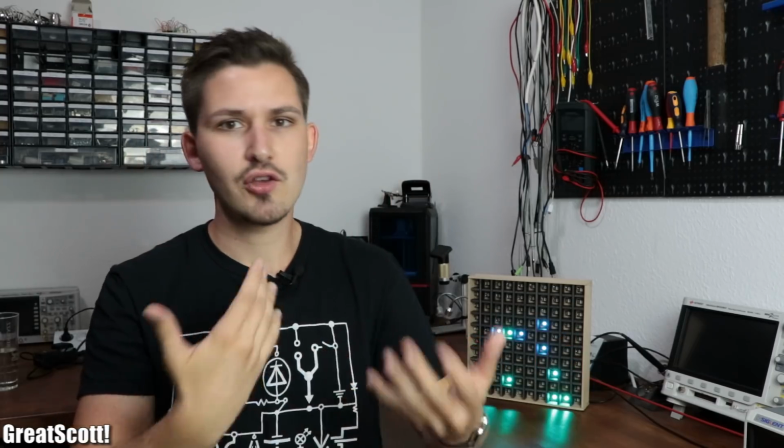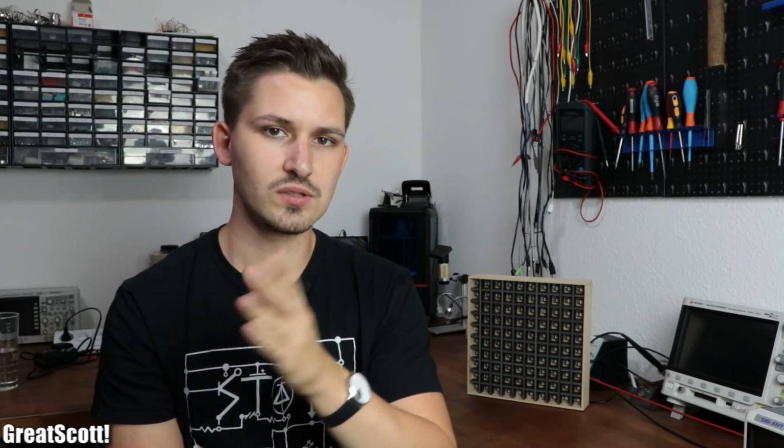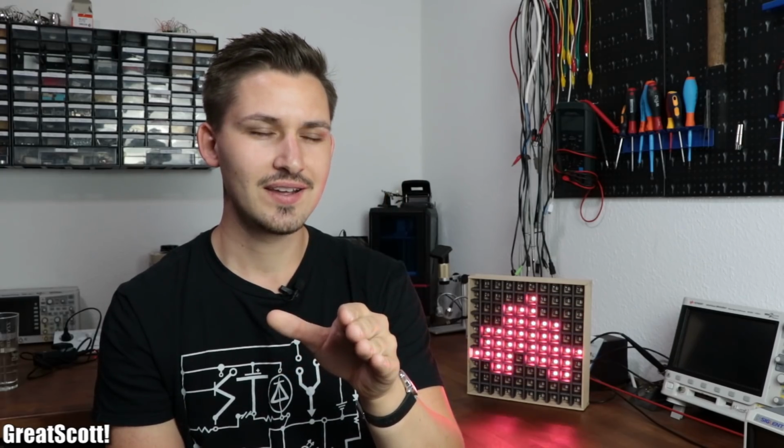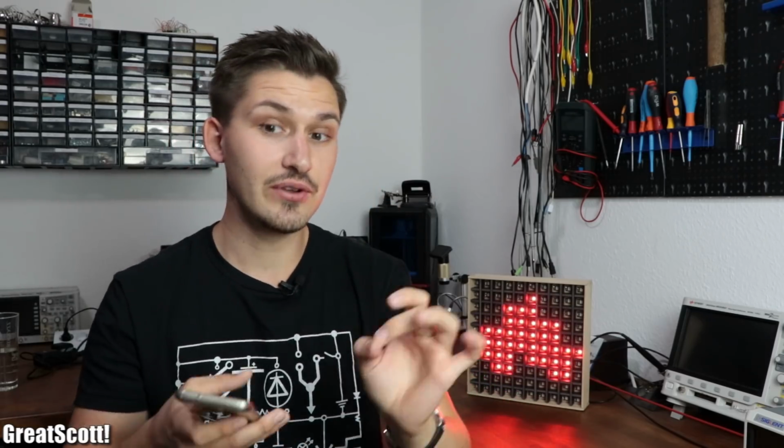And that is then calculated to your 15 volts. It's just 24 watts divided by the 15 volts that you want, and that should be around 1.6 amps on the output. So with your 2S batteries, you should be able to get 1.6 amps at 15 volts. So you got 24 watts, which is derived from the maximum input power of 30 watts, but you got an efficiency of 80%. So that's how I would calculate it. Could be wrong. I think I just made it up the way I think it should work. Feel free to correct me in the comment section if it is wrong.